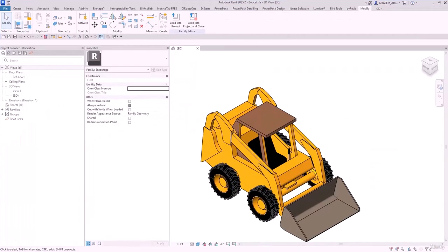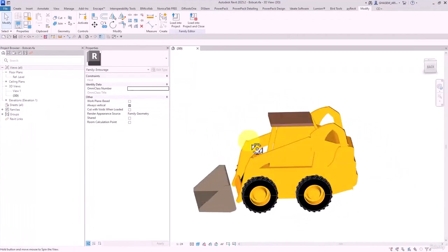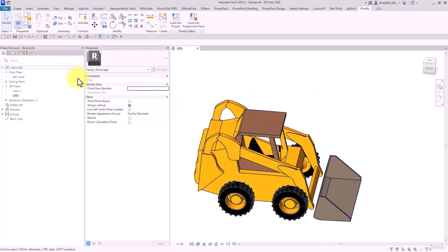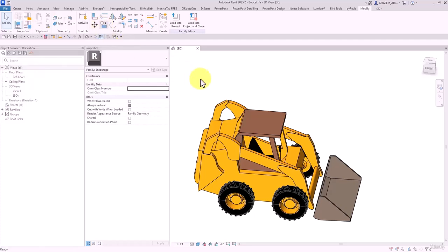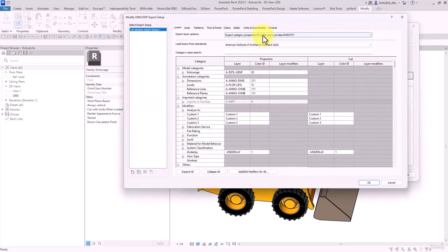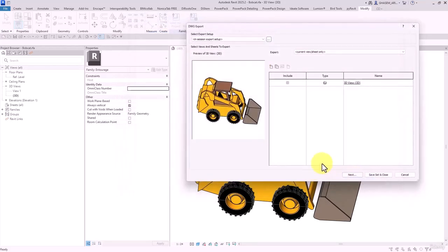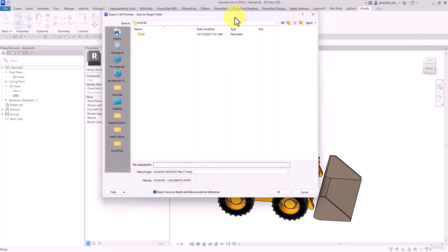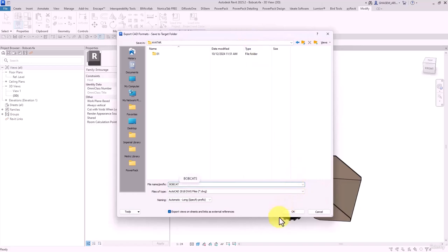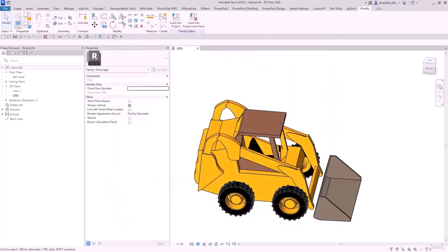In Revit Structure or SketchUp, 3D Max, or every kind of software that you want to consider. If, for example, we want to export this file as DWG, CAD format, directly, actually we can have NWC from Revit, but because I want to change the direction of what we are seeing, I will first export DWG. I will do the settings in AutoCAD, and then I will go through Navisworks. So a file will be created in here, and the name of that, for example, is this, and save it. This file has been exported in a path that we wanted.